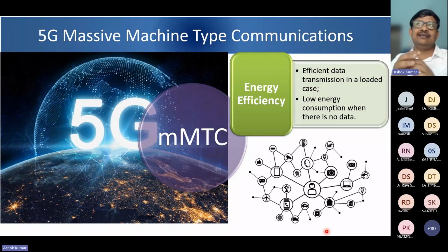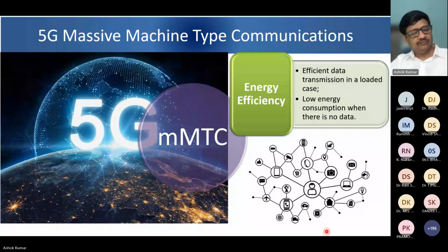So here, as I said, devices would be installed in very, very far away remote areas. So how do we cover a far away and remote area? Through satellite also we can connect. But basically, I'm talking about a 5G base station. If I have a 5G BTS which can cover a larger distance, and to cover a larger distance, what should I do? Increase the transmitted power, the height of the antenna. You have to use the low band. Very right. 700, 600 megahertz band. Very right.